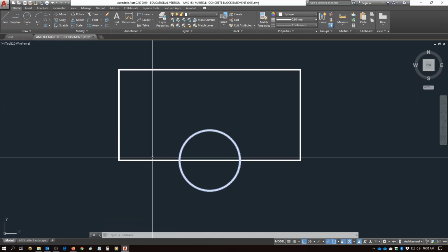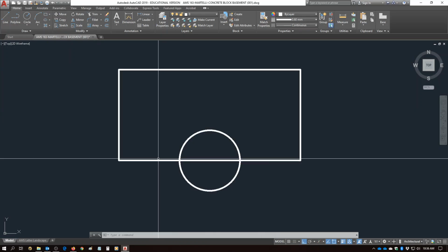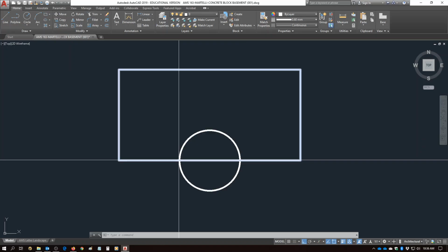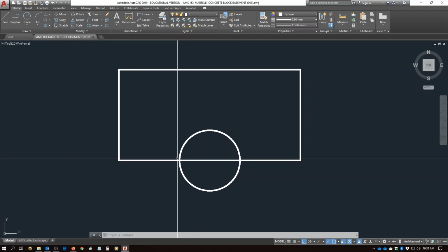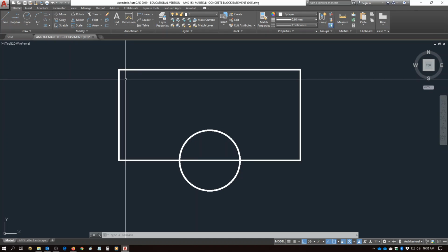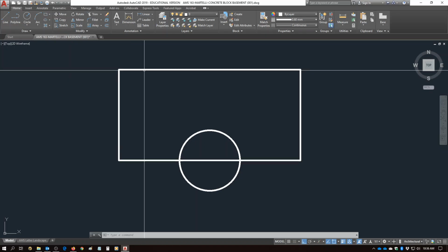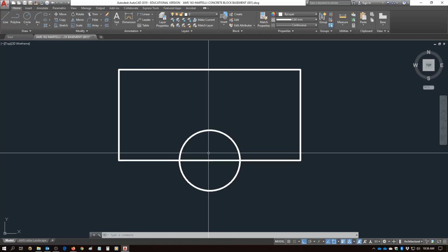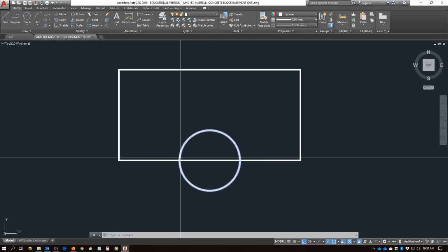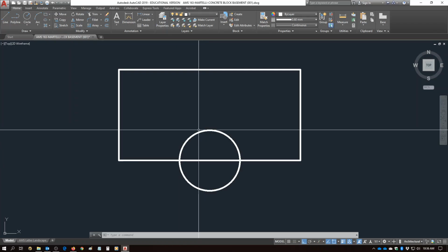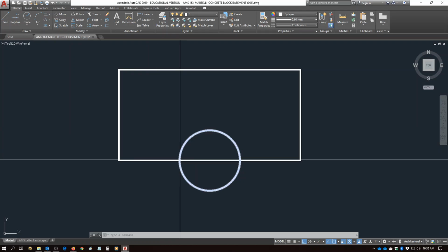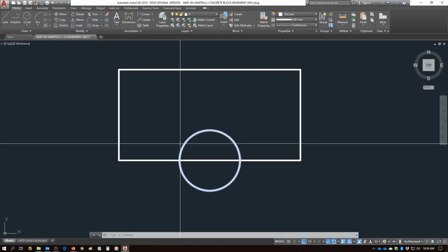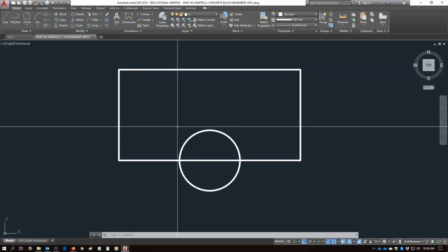The upper quadrant, well, that's going to be 1/3 the height of this footer. The diameter across is going to be 1/3 of the length across. This footer happens to be 16 by 8. 16 by 8 in ratio is 2-to-1. So radius and diameter are 2-to-1. So what this does is I imagine that there's an intersection. If I were to follow the upper quadrant across horizontally and follow this left quadrant vertically, there would be an intersection right about here to put my rebar.